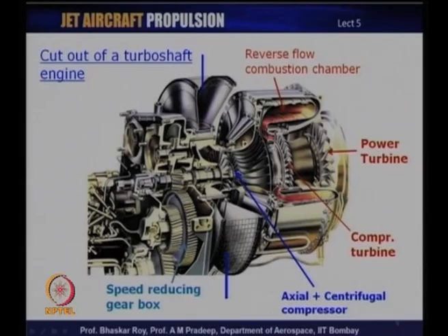So, this inner shaft comes through the outer shaft from here, and then through this gear meshing system reduces the speed substantially, because as I mentioned, the turbine speeds are likely to be of the order of 8 to 10,000 rpm, sometimes even higher. A compact engine like this could have speeds of the order of 30 to 40,000 rpm. That is the kind of speed at which many of the turboshaft engines could actually be running, and as a result the power generation is of very high order.